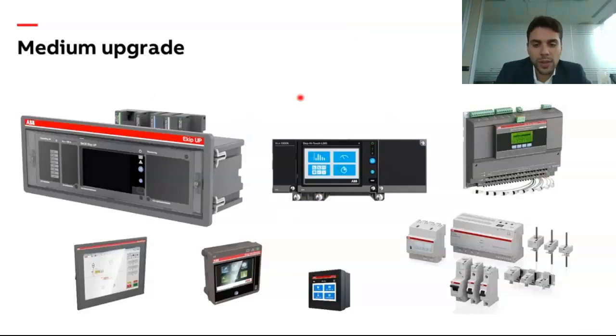So if you start with the simplest trip unit, you can upgrade to more digitally advanced and unlock new features such as monitoring of the power quality, energy, then also the total harmonic distortion, etc., voltage, current, power factor, at a later stage, just by changing the trip unit.